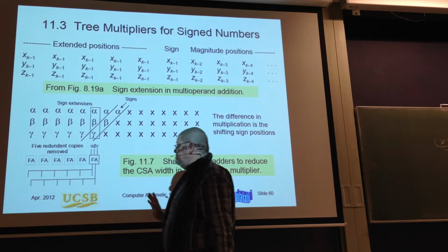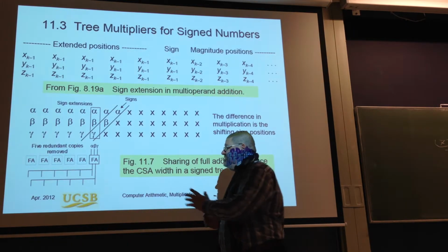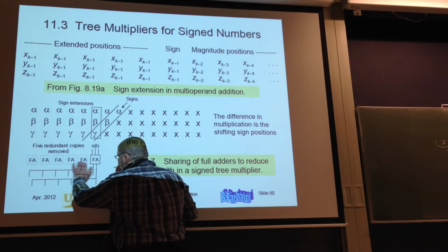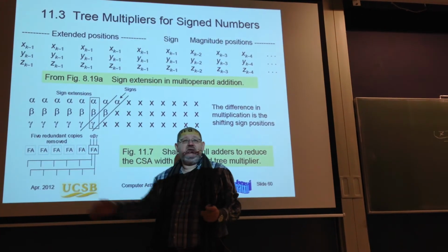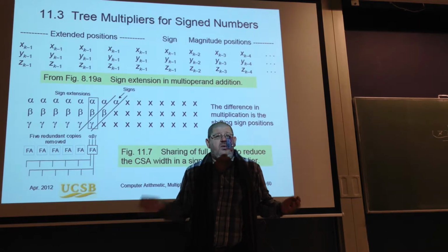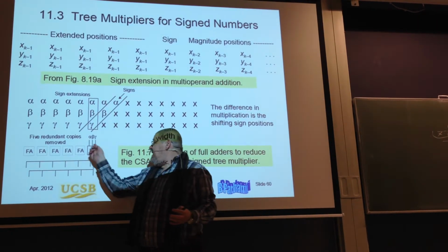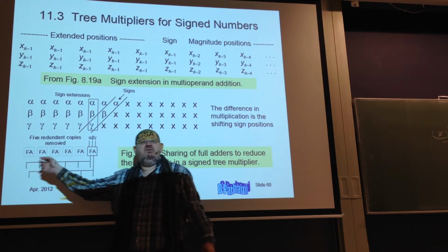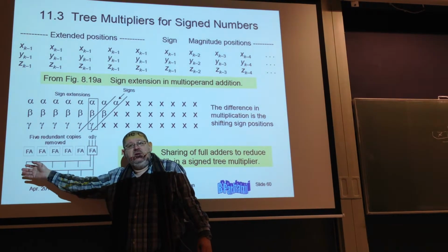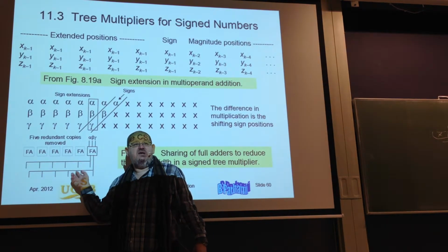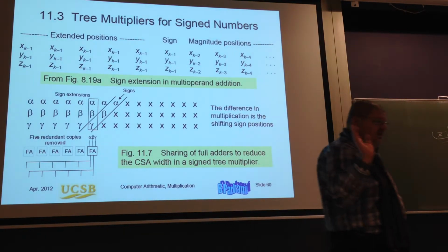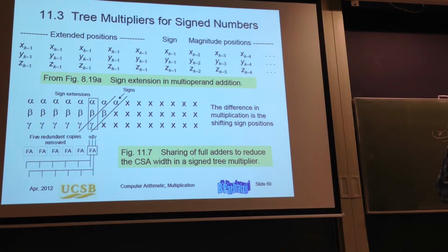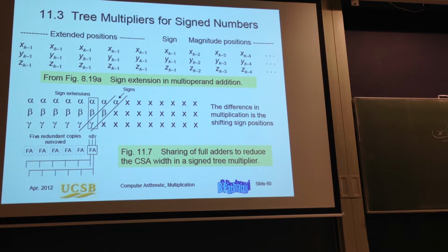And then I have two solutions. I have the solution to make copies of that, then to apply the same full adder n times, or I have the solution to make one, and this one will drive all the full adders which are consuming this result. I think I mentioned that, but I will do it again. Both of them have advantages and disadvantages.